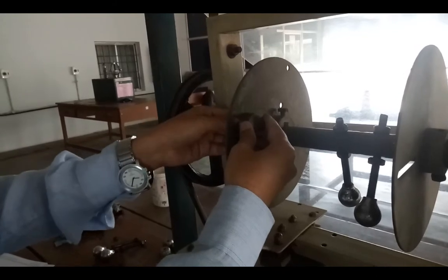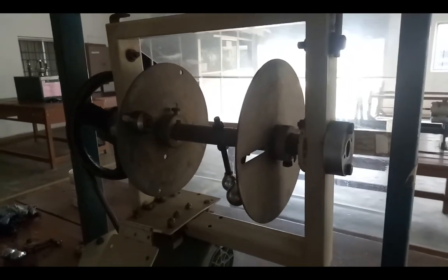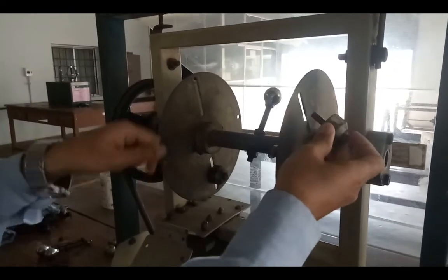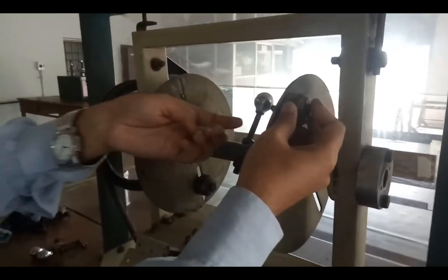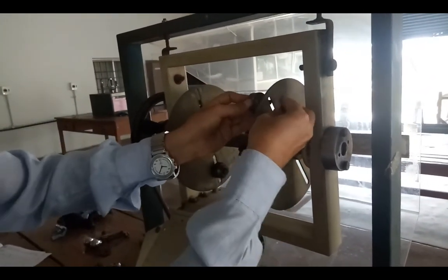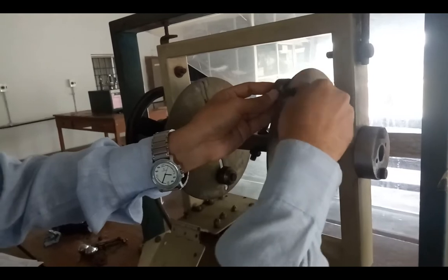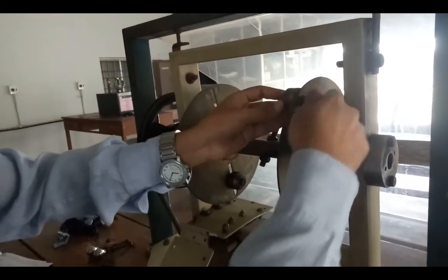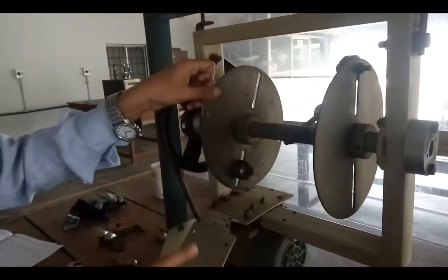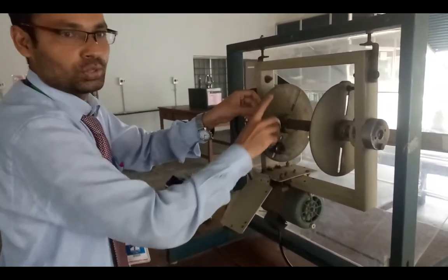Here this is one part. Second, the mass of C, which came to 0.186, you are also going to fix, and here you fix it in the opposite direction, not the same direction. These two masses you have to fix in opposite directions. If you fix them like this and start the machine, it will be completely balanced. I will repeat: these two weights we fix based on what you got in the calculation part, and while fixing, they should be in opposite directions, not in the same direction.